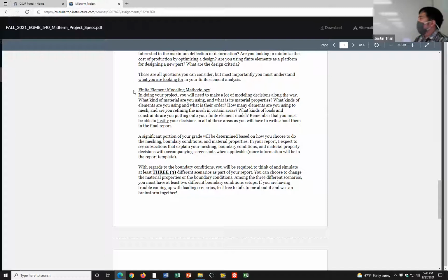These are all questions that you have to answer as you set up your finite element simulation. I want you to be very detailed, first of all, in listing out what you did, because that's an important part of any finite element simulation: being clear about all the settings and all the parameters that you chose. But more importantly, I want you to be able to justify your decisions. If you chose a hexahedral mesh, or a quadratic element order, I want you to be able to explain why you're doing that.